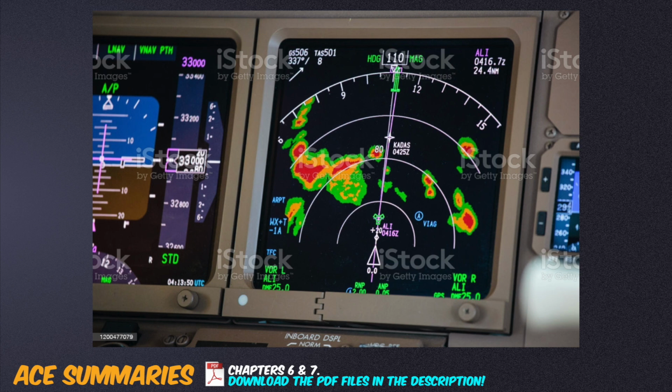The electronic flight instrument system color coding is as follows. Green means active or selected mode, or changing conditions. White means present situation and scales. Magenta means command information and also turbulence if the radar display is active. Cyan means non-active background information. Red means warning. Yellow means caution.